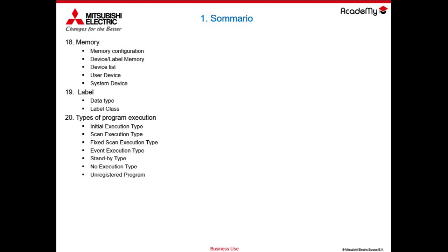We will also talk about module labels, so labels associated with the smart modules present on the PLC iQ-R in our configuration. In this case, the GX Works tree gives the possibility of adding these module labels with which to program an interface and also to define the local variables.